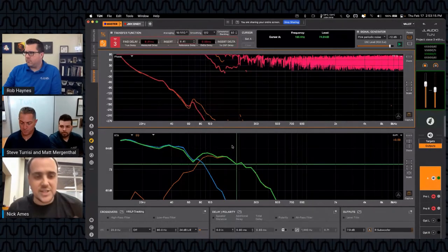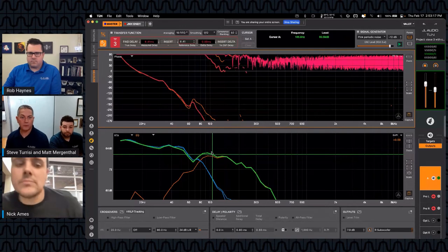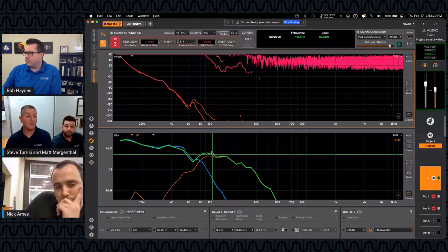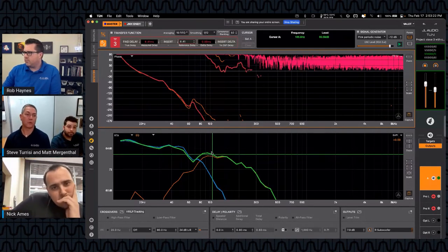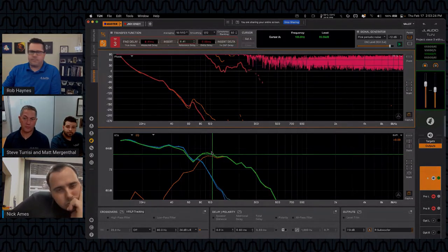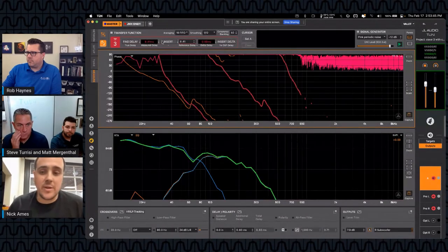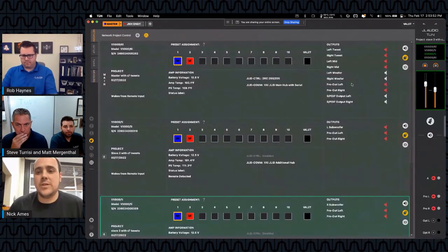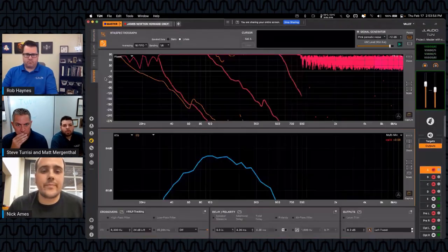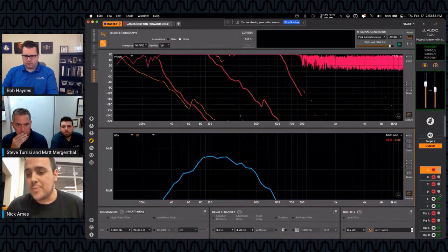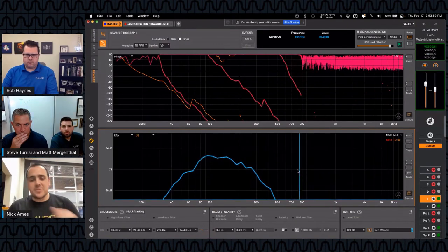So Steve, you said something about all-pass. I'd love to see if we can, hopefully there's a need for it, but if not, can we force it just so we could show what that does and how that would show up in phase? I suppose there's a couple ways we could go about doing that. You could just place an all-pass filter on purpose in one of the mid-bass responses.